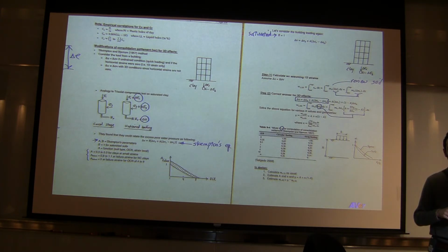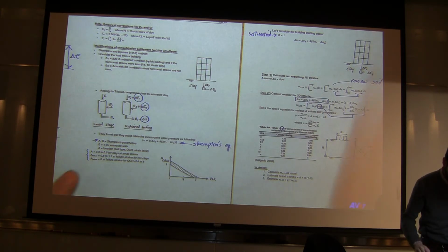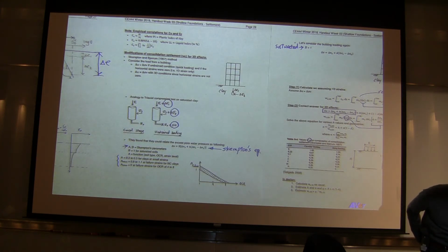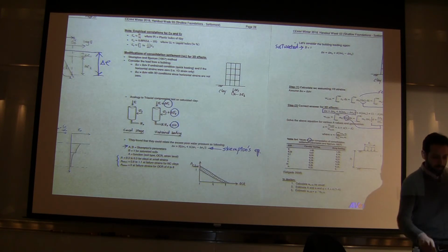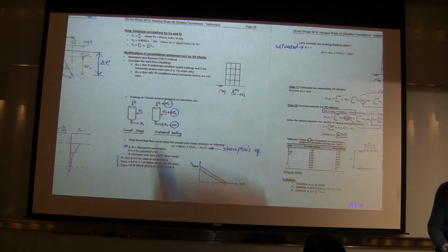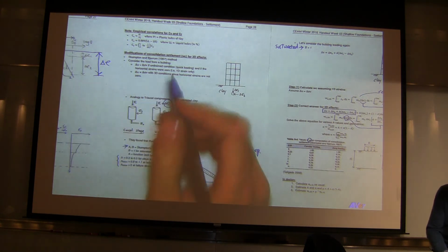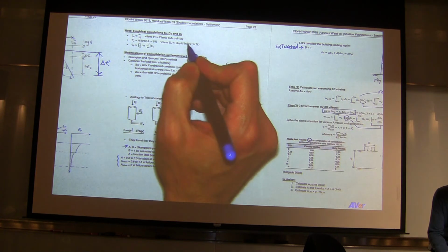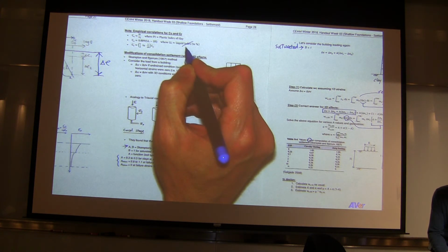Any question? Robert? Yeah, I have a quick question about the empirical correlations for CC and CR on page 28. For the CC calculation, it has LL minus 10, which I would think would be the liquid limit, but here it says the liquid index, which I'm not sure is a percentage. The liquid limit is a water content, right? So that would be a percentage, but the index is... You're right. Thanks for picking that up, this should be liquid limit.